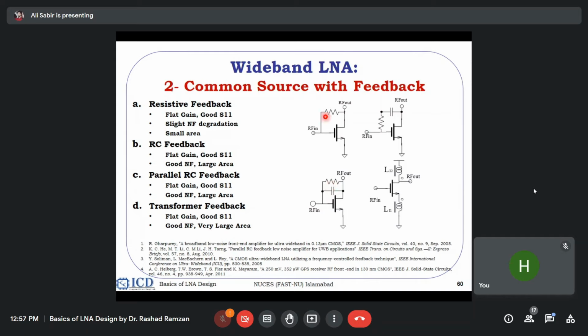You can see here we have a resistor feedback, here we have an RC coupled feedback, here we have a parallel RC feedback, and here the feedback is a transformer. How? Because VGS is actually V in here and minus V out here. So this is actually a feedback inductor, and this is coupled with this inductor. So these are all four feedback mechanisms for wideband LNA: resistor feedback, RC feedback, parallel RC feedback, and transformer feedback. So we can get the 50 ohm input impedance using the feedback.